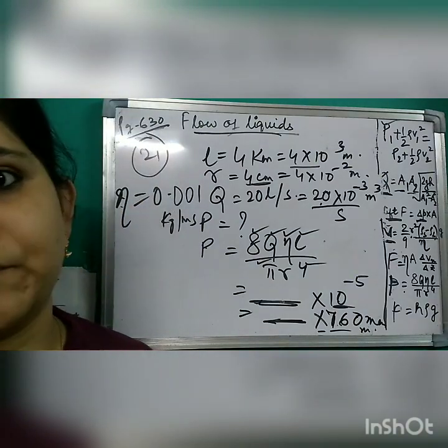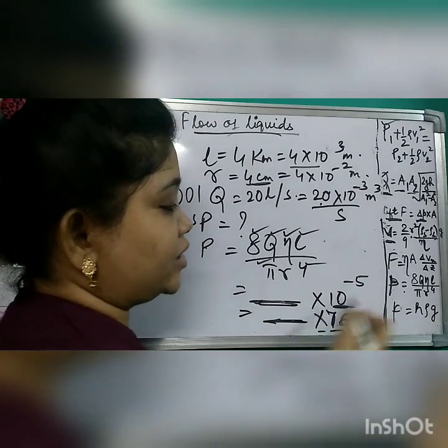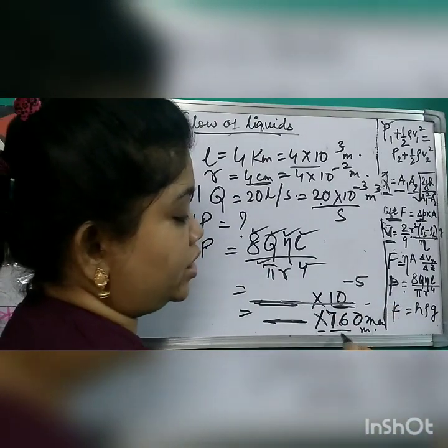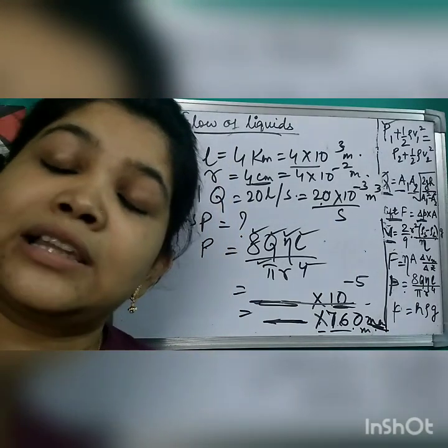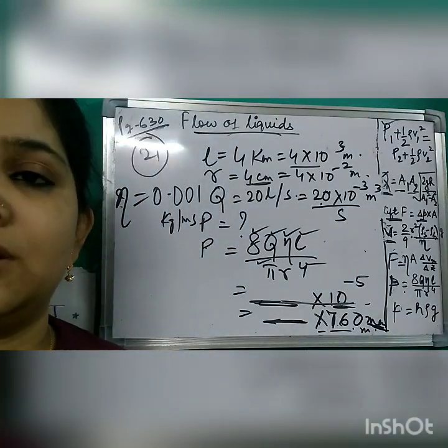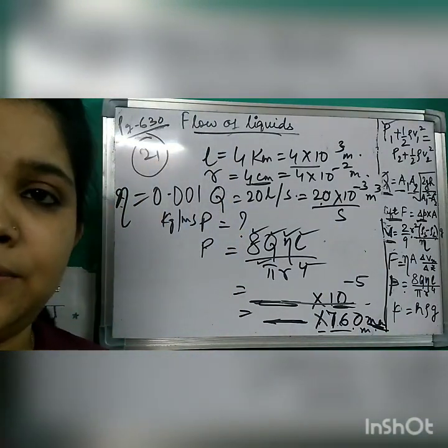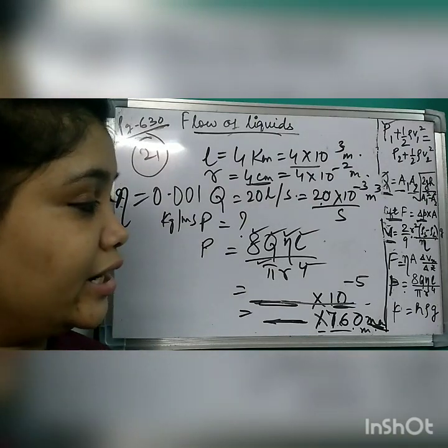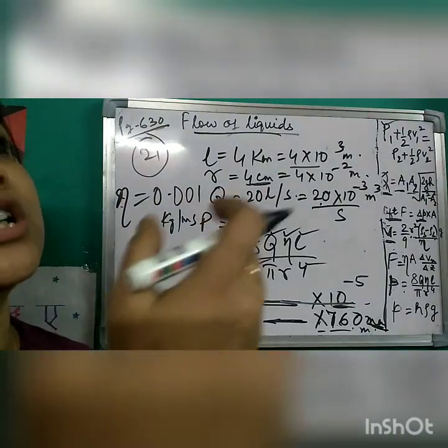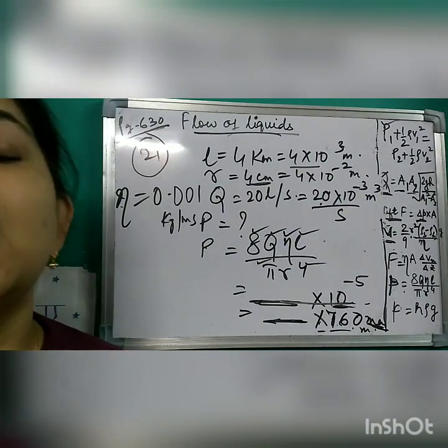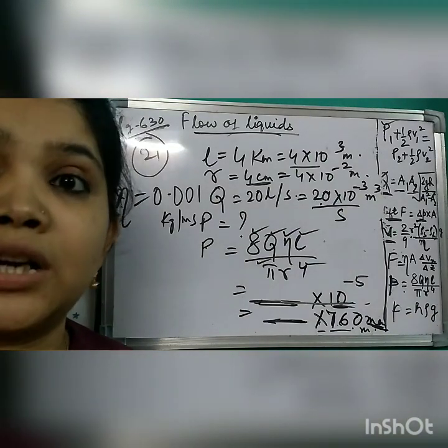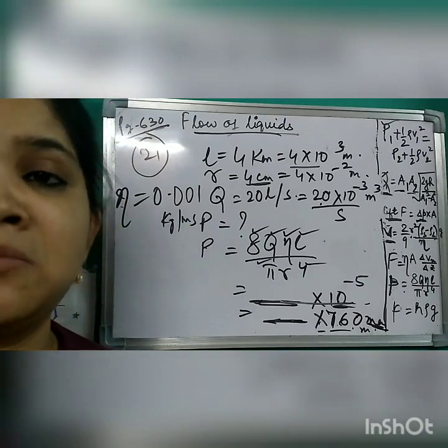Hg means mercury. Then convert the millimeter into meter and you will get the answer. So here there are two conversions. One, you convert the pascals into atmospheric pressure, and after that you convert into height in terms of mercury, which is multiplying with 760 millimeter of mercury.